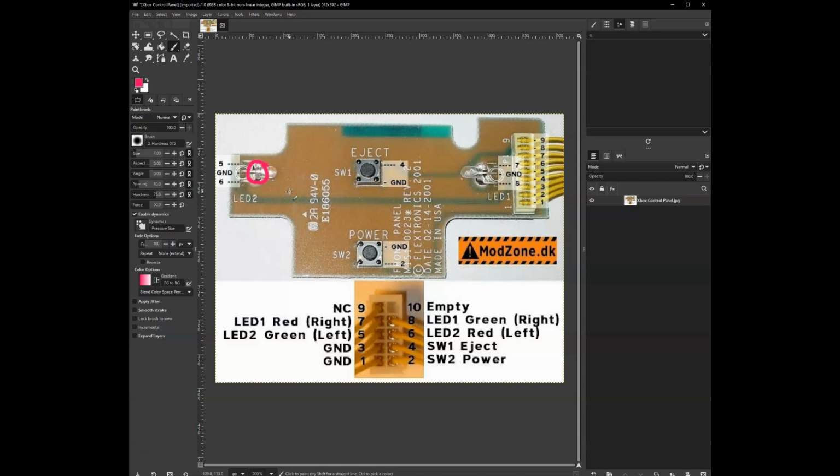I got some LED lights off of Amazon that I could use with my motherboard, and I basically soldered 2 of them together to be able to put on the same port on the motherboard. Since the LEDs that I have were actually larger than the actual LEDs on the Xbox, I had to drill out these sections where the bulbs were a little bit larger so they would sit in it. Once I did that, they sit fine. I used some hot glue to fasten them in so they wouldn't come out.